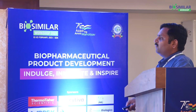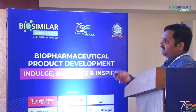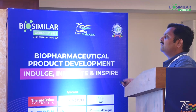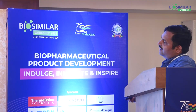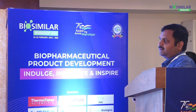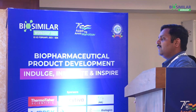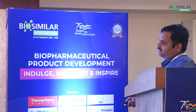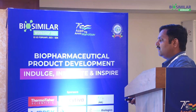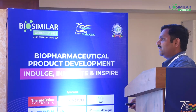Now before we move on, I think we have seen a similar figure in Rahul's presentation. The mass transport processes working near the bead are film diffusion, adsorption, pore diffusion, axial dispersion, and surface diffusion. And this is well explained by the general rate model. Mass transport in the column happens because the solute moves through the interstitial column volumes with the convective flow. The band broadening issues are explained well by axial dispersion and resistance because of film diffusion and pore diffusion, as well as the surface diffusion and the adsorption inside the bead particles.